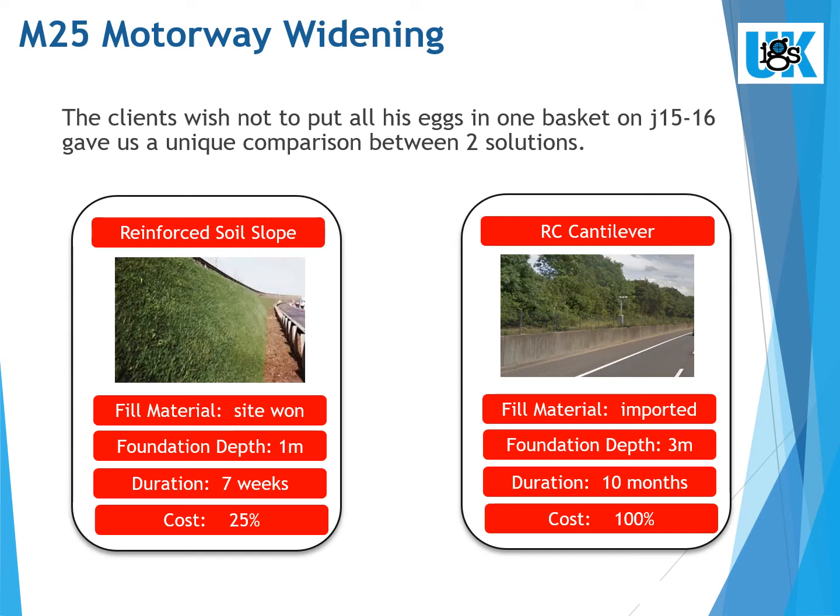This side-by-side comparison highlighted the benefits of the reinforced soil solutions, including the reuse of the site-won fill material, the reduced depth of the foundation works and subsequent safety improvements, and significant reductions in both construction time and costs.